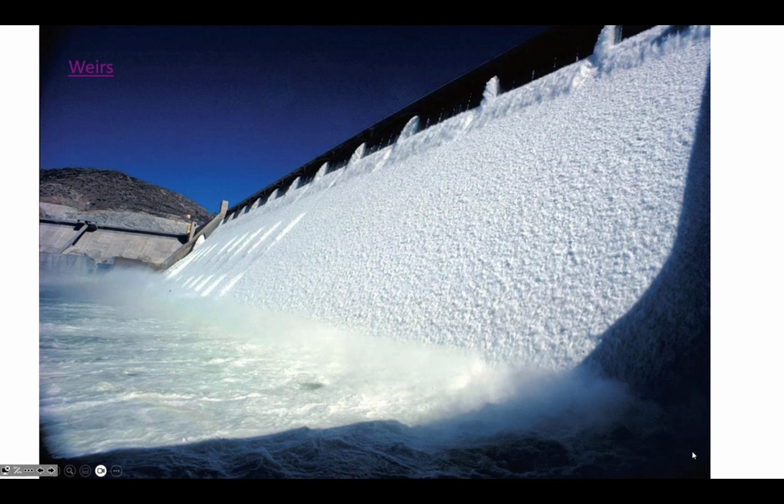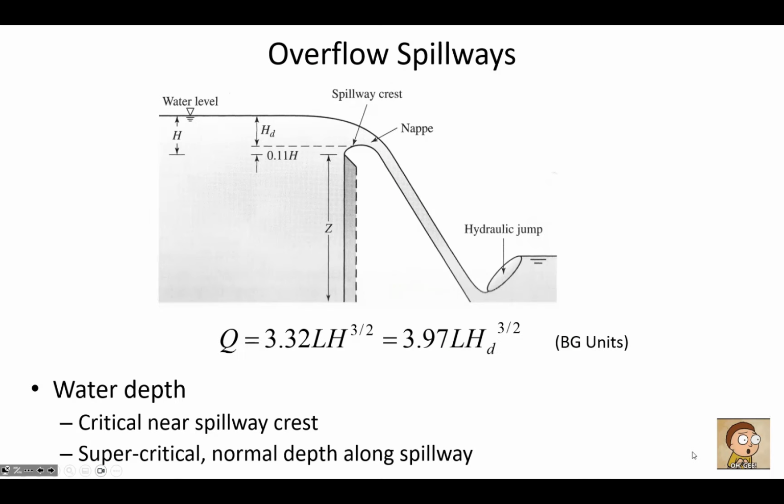So that same trick that it was showing with the folded weir is used in clarifiers, where instead of just a single flat weir surface, they would have a zigzag pattern that basically increases the length, where the total length would include all of those ins and outs. And so that sawtooth pattern is one of the tricks that they use in wastewater treatment to increase the area, and that decreases the velocity. So this has application not just to water resources, but also to environmental engineering as well.